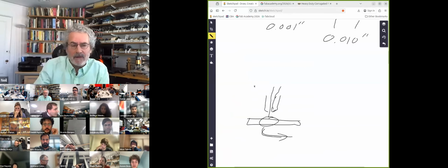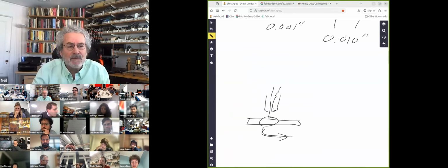Now, in this volume, you're creating gases, you're creating combustion products. If everything works well, it goes through the exhaust. If you look in a laser cabinet and you see smoke, it's a terrible sign. It says the exhaust isn't working. You should stop right away.